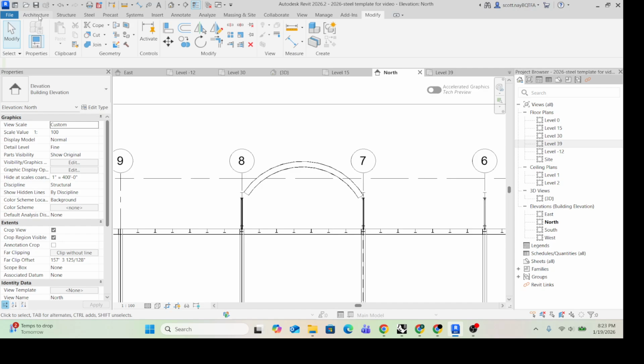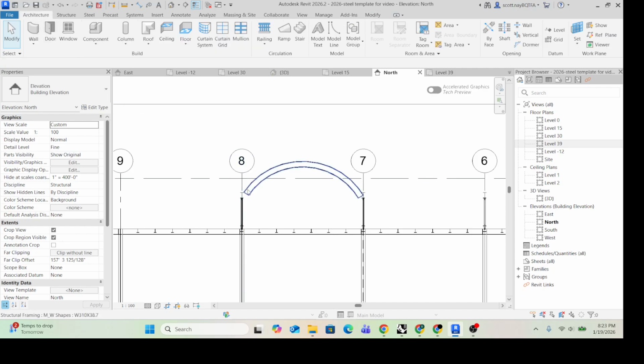I'm going to come into the Architecture tab. So we can't do footprint because we can't determine a slope on this. And if we try and do massing, we're going to run into a similar problem where if it sees two of the same thing, it's going to interpret that as a center point and an edge of a circle, and it's going to make this giant circular mass going in the wrong direction. So we want to go with by extrusion.